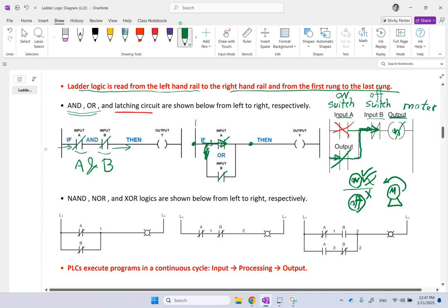This path becomes AND between this output variable and input B, and this one still receives a 1 and stays on. Do you see that? So it keeps looking at the previous value of it, and as long as this is on, once you pressed on the input A once, the on button, pressing more on it will have no effect because this path is always open. So when would you stop the motor?